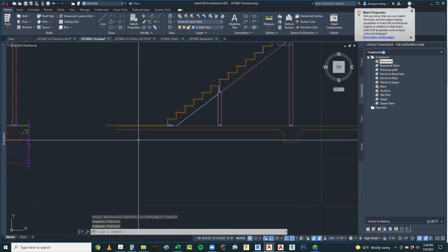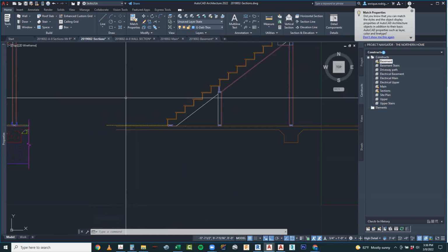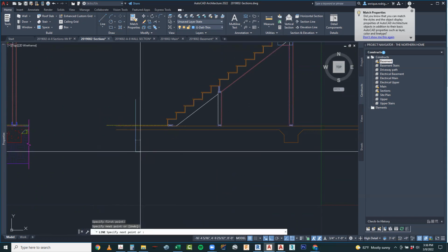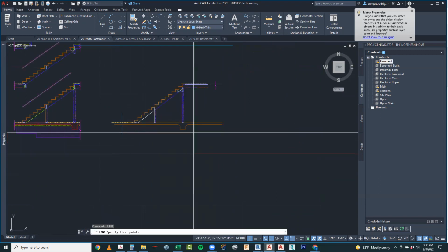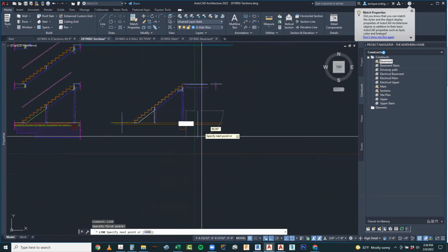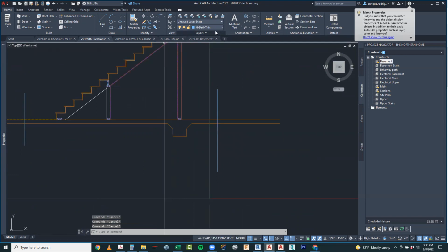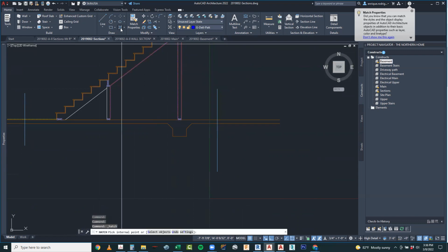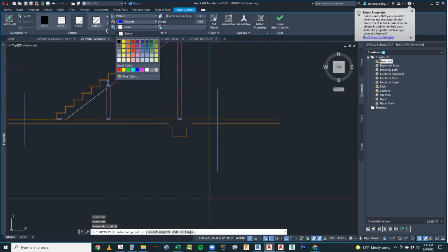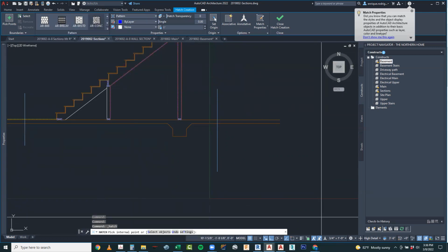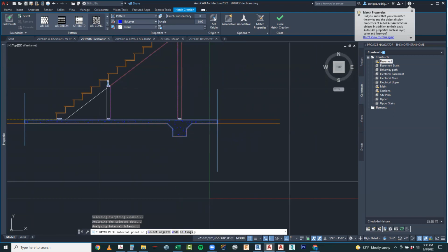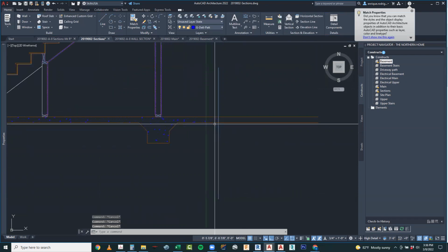Now I'm going to go ahead and close it off so I can hatch it. So I'm just going to draw a line right here. We may have to cut that back a little bit more. And another one right here. I'm going to go to G detail pattern. Go to hatch. Find my architectural concrete. I'm at 3/4 inch already, and I'm just going to hatch right in there. There's my hatch.